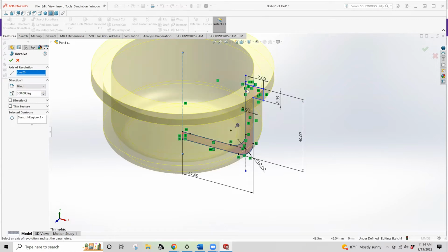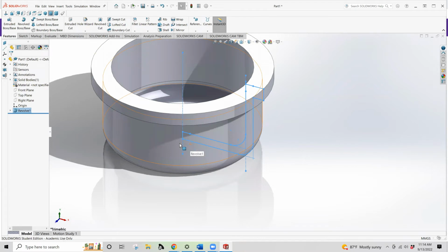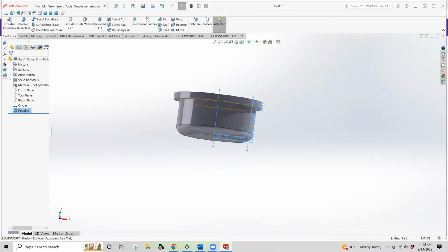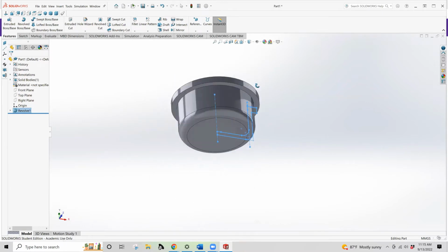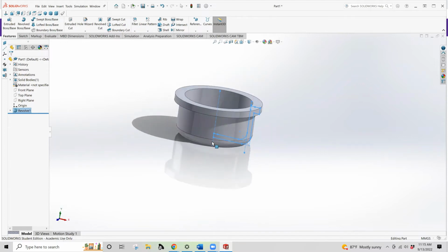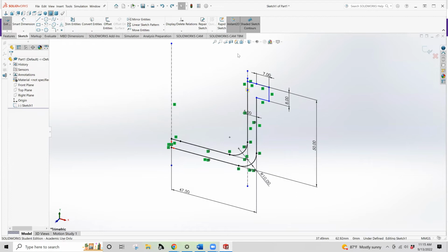Now, because it's able to interpret some things correctly here, it's probably able to create our object. But just because it can do the operation doesn't necessarily mean it's correct. And I didn't finish some of the sketch filleting on these other two corners because they're going to be a different radius, so we'll go back and make a base change. I just wanted to show you where the thin feature actually comes up. So we're going to undo that operation and go back to our sketch.